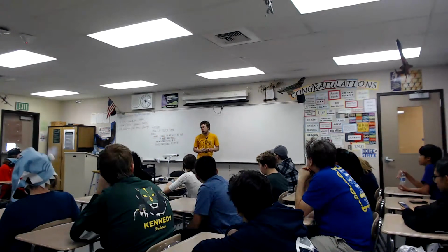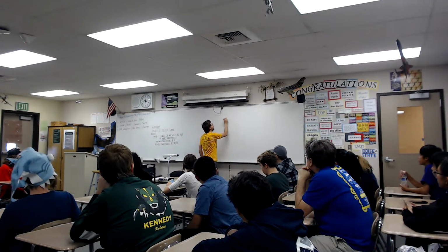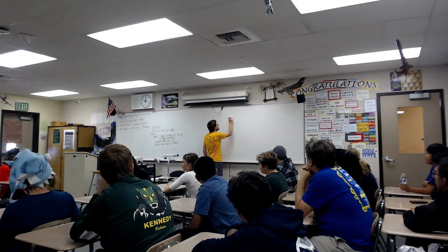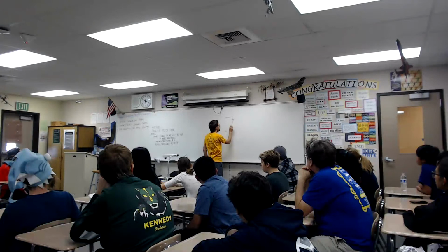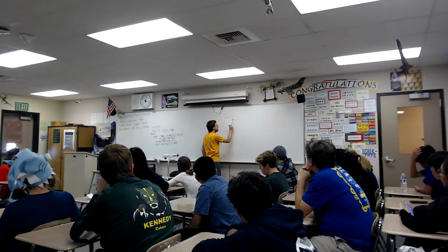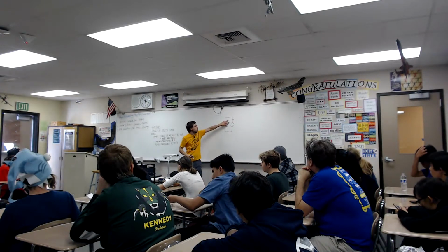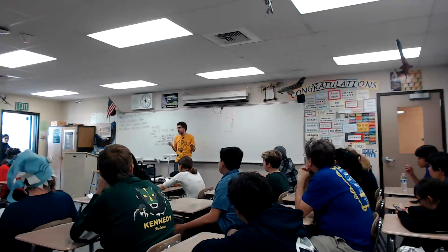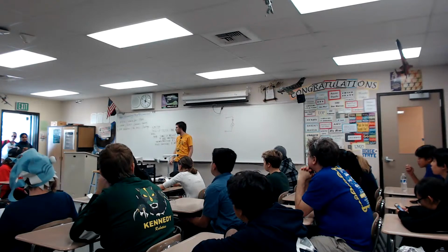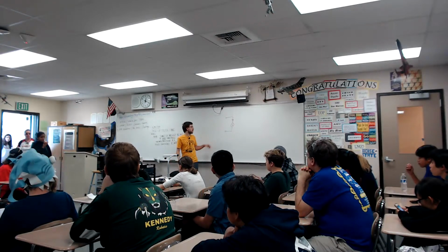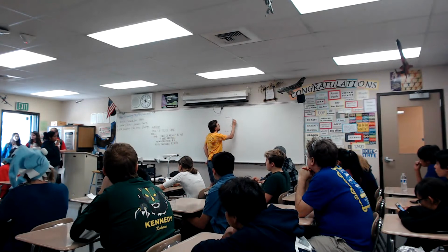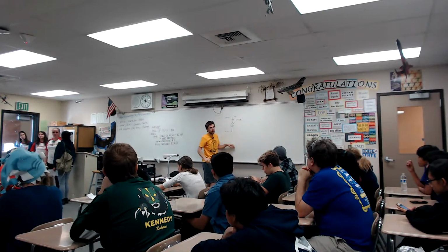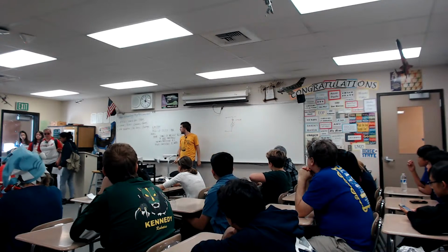This is a basic brushed DC motor. You have an input and an output. A motor is modeled as a resistor and a generator. If you think physically, the resistor is the copper in the windings, which has resistance, and so that's going to resist voltage. So we're going to have the voltage across the resistor, V equals IR, our famous Ohm's law.